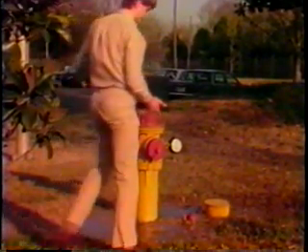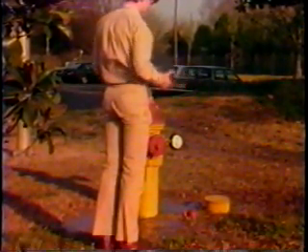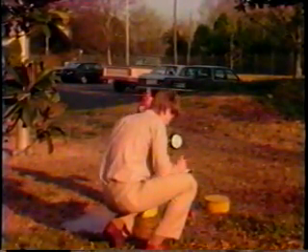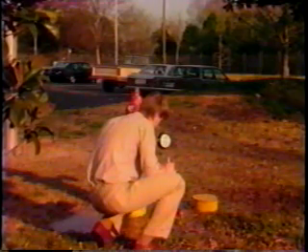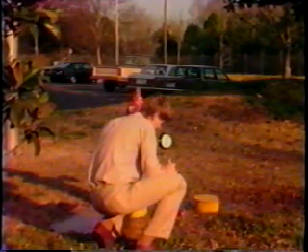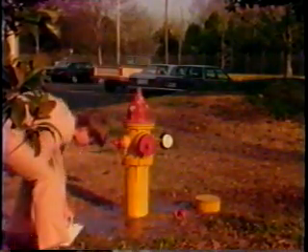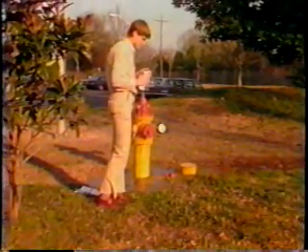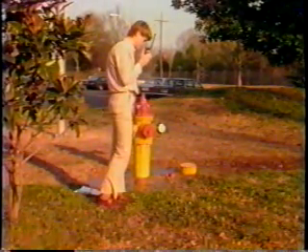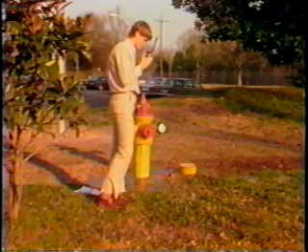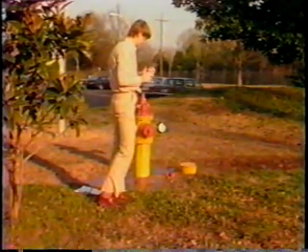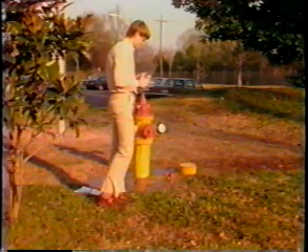The pressure gauge should not be bouncing around too much. If it is, try to find out what's happening. Are pumps kicking on and off nearby, or is a pressure reducing valve opening and shutting? Usually though, the gauge should remain fairly stable within 1 or 2 psi. Once you've recorded the static pressure and are satisfied with the reading, it's time for the individual at the residual hydrant to contact those at the flow hydrant to see if they're set up and ready to begin the test.